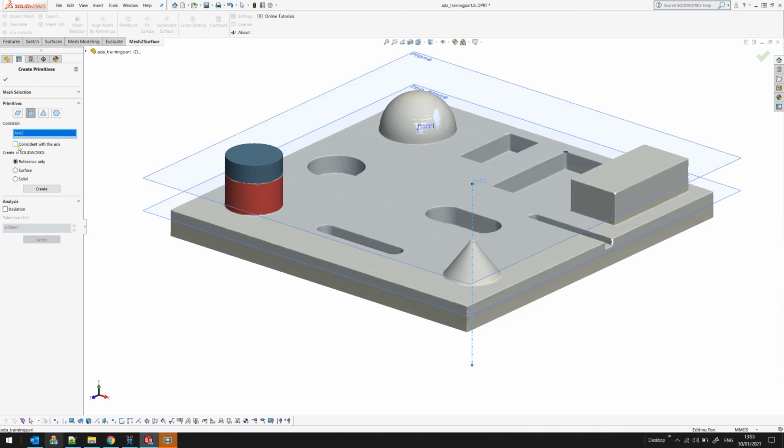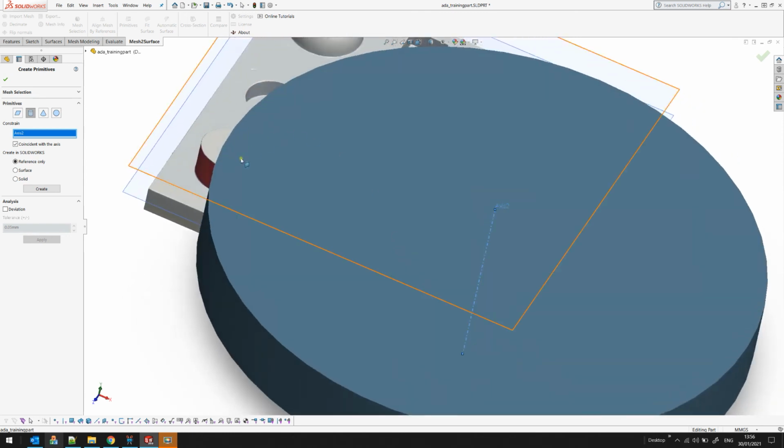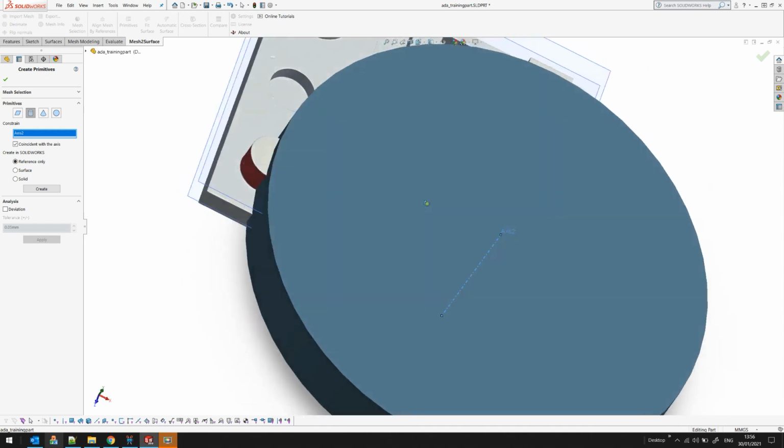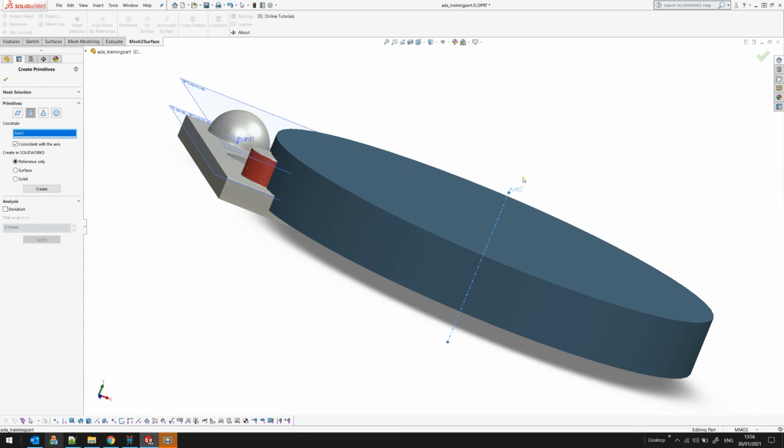There is a checkbox here, which in other examples you may use when you have two coincident cylinders or cones. In this case, what you want to do is tell the software to do its best to fit through the points, but I want my axis to be coincident with my given axis, which in these examples doesn't give expected results, but everything is correct because it complies with the expectations.